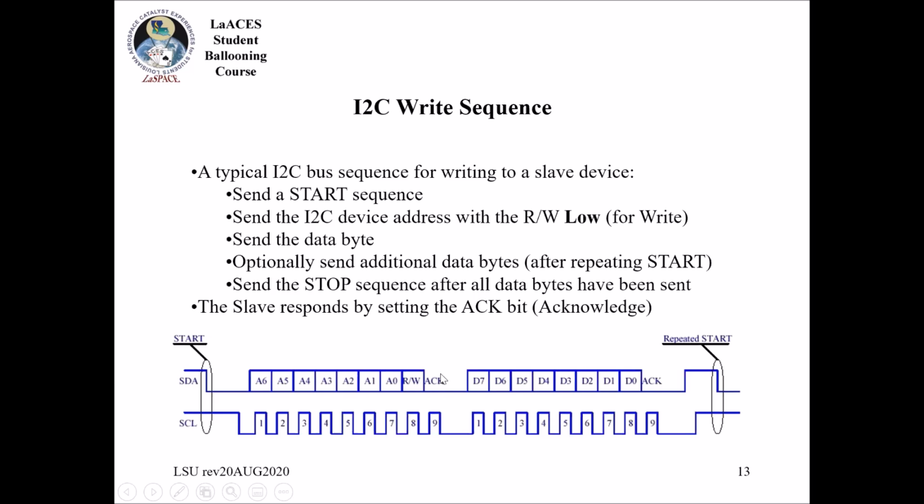And then number 86 is going to come in and give a little tug on the line that says, I acknowledge you. Or sometimes there's something called a NAK, which is does not acknowledge. In this case, we got an acknowledge from number 86, so we're good. Now the master is going to proceed if it receives this acknowledge. So if you ever have something hooked up and you're only seeing 1 byte being sent, or something weird, something's not hooked up right and your other device is not sending this acknowledge.